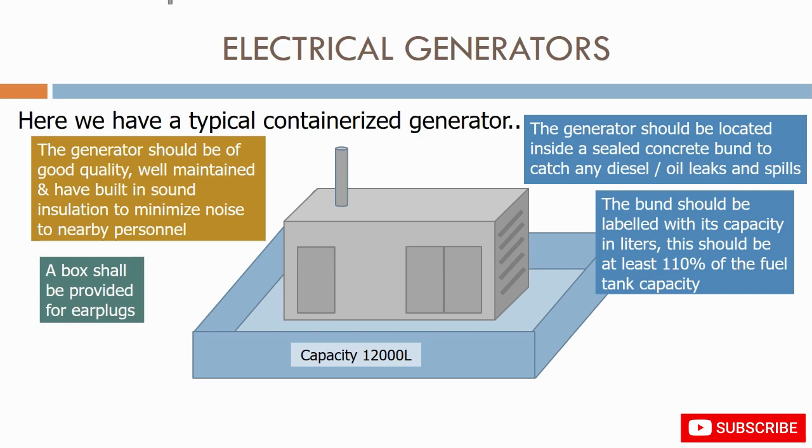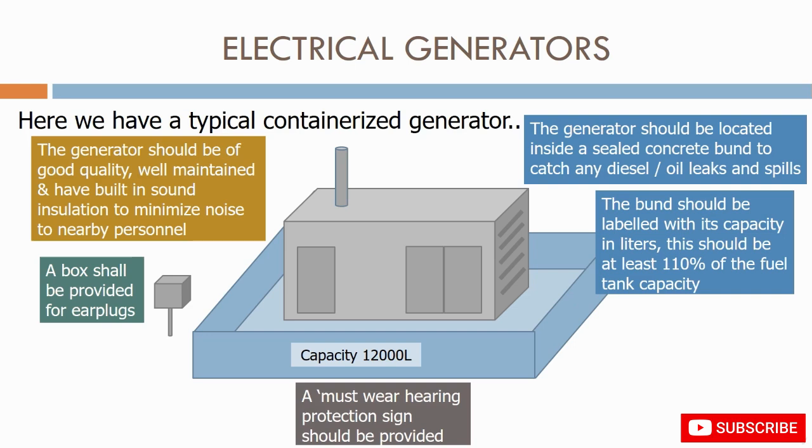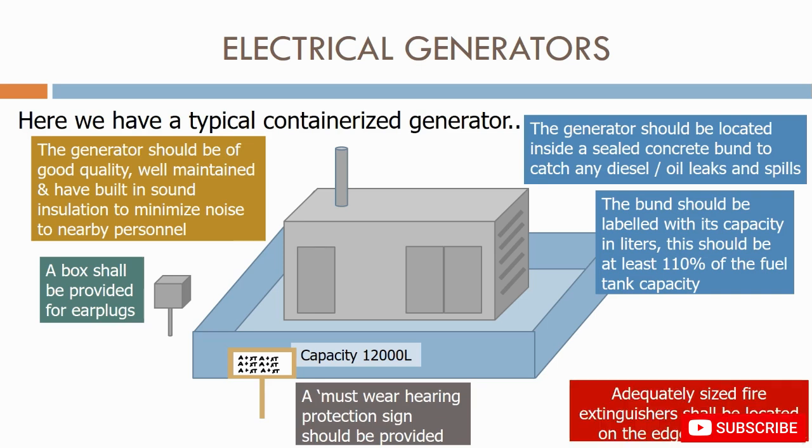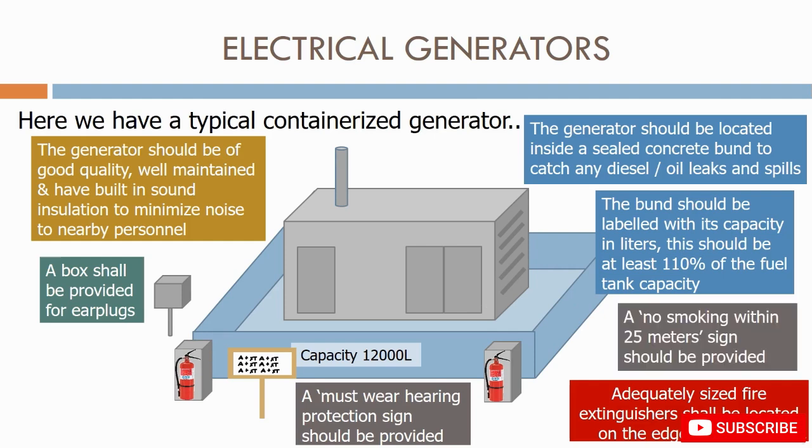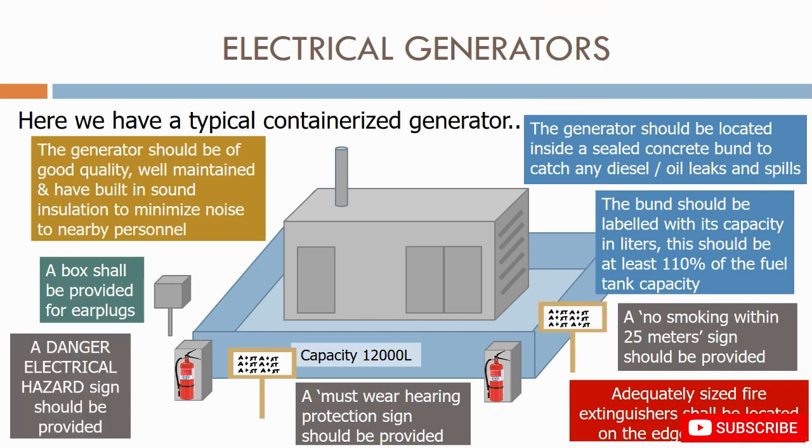A box should be provided for earplugs. A must-wear hearing protection sign should be provided. Adequately sized fire extinguishers should be located on the edge of the bund. A no smoking within 25 metres sign should be provided. A danger, electrical hazard sign should be provided.